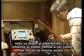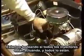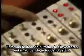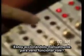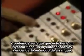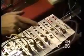Let's hook up the distributor and just rotate the engine because I want to see what it looks like with the same pulse. Just testing to see if all the injectors are firing, and they are firing. I'm actually turning it manually to watch it fire. Okay, and you can see right here, this one has an injector. That has an injector. Now I'm going to turn it the way the car normally runs.